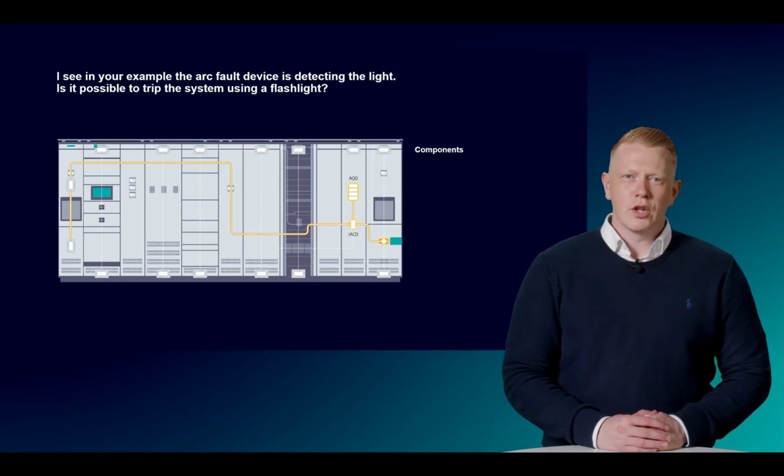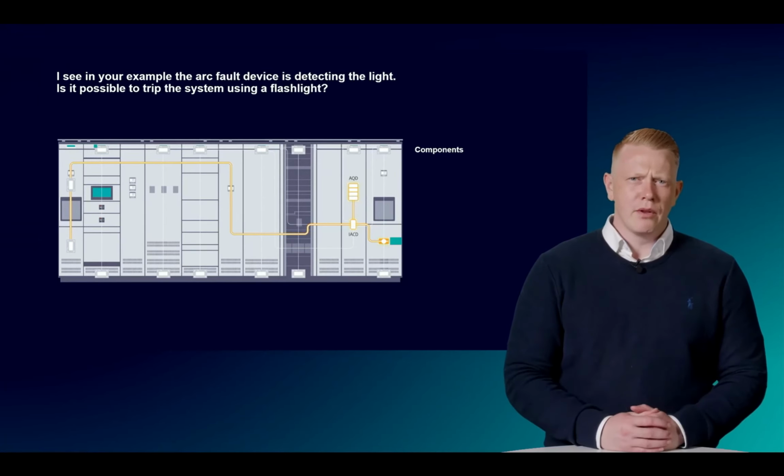Next question, does the system use protective core transformers or normal transformers to measure the current? The system works with normal transformers, as not the absolute value of the current is required, but the rate of change.